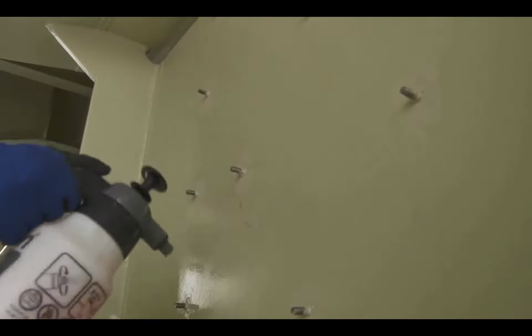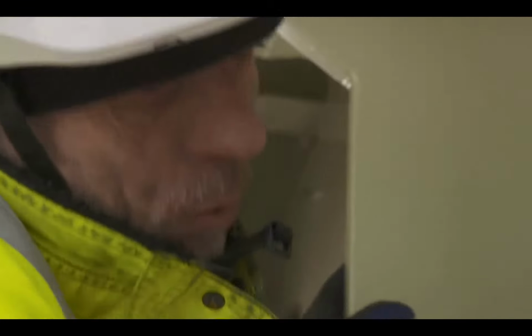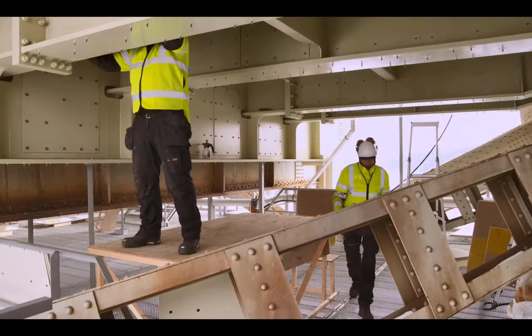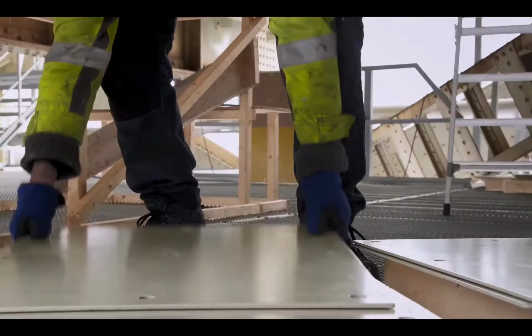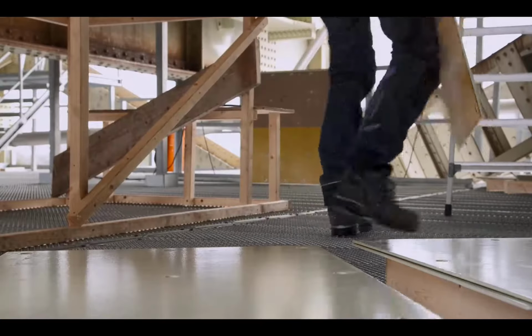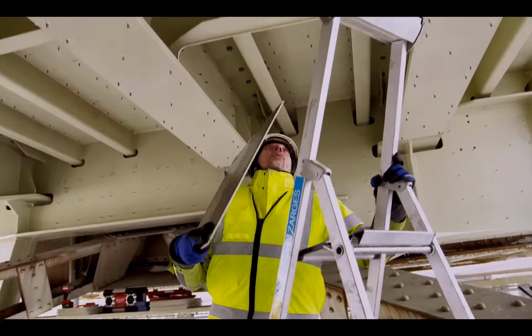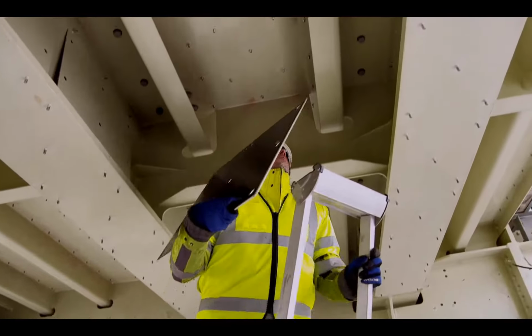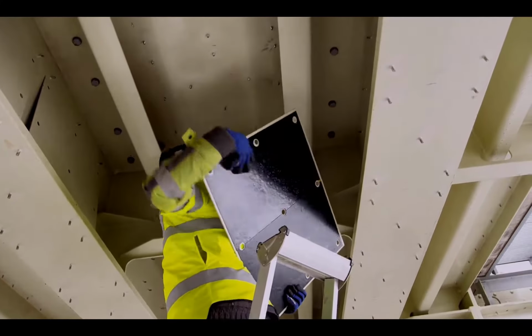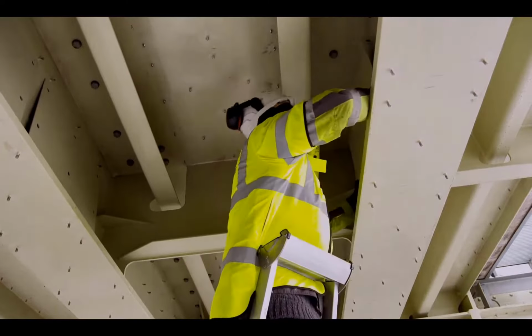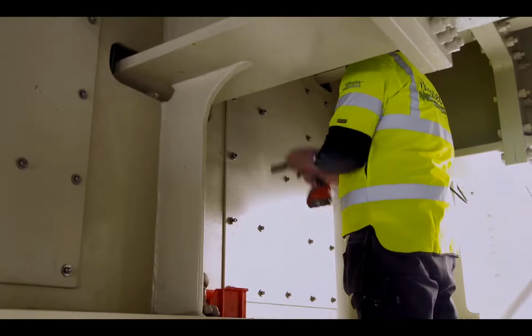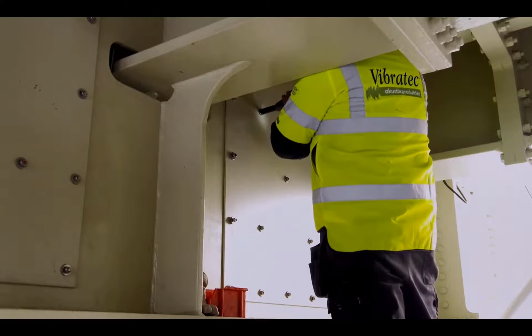Before any mounting could begin, the surfaces were carefully cleaned to ensure an optimal contact between the noise damping coating on the panels and the steel structure of the bridge. Following this, around 5,000 panels were fitted. There were 270 different shapes to make sure that every part of the bridge could be covered. The panels were painted in the same color as the bridge, not to affect its appearance, which was important considering that the bridge is classified as an historical landmark.